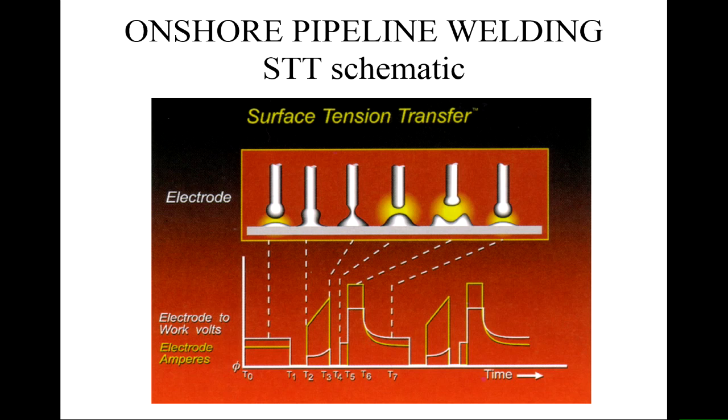Now you want to break that contact. So again, you switch off the power that's supplied, and then you switch on a voltage, and at a certain period you get this necking that you can see there, where the heating is focused on that very small area, and effectively you break that contact at this particular point here, and then you get an arc again. But now we have a flat-ended wire and a hump of weld metal that's been deposited.